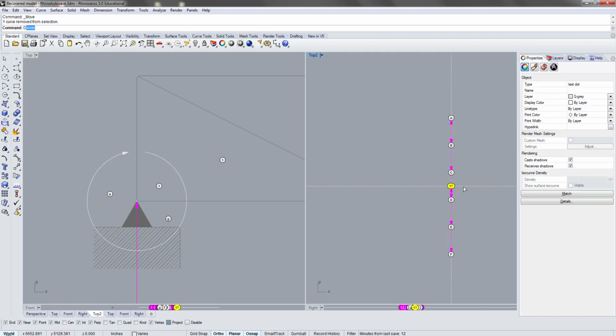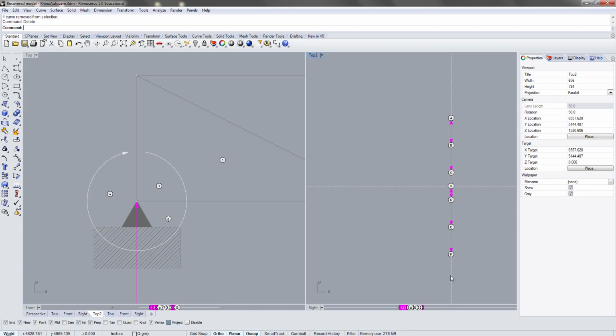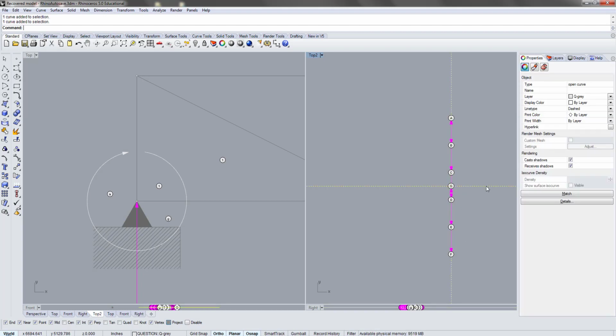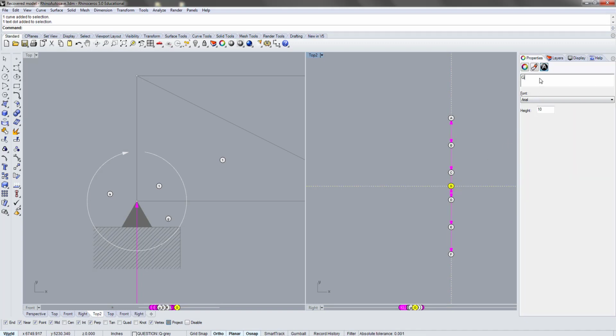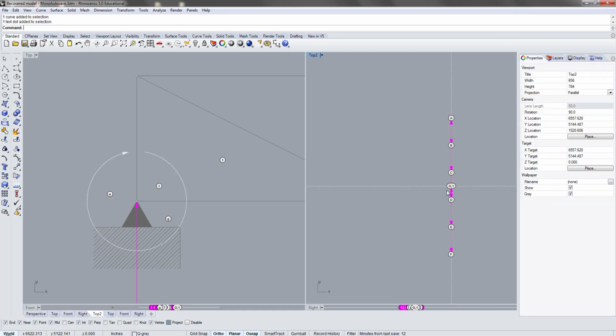So now what we know is that point 1 is on this vertical line as well as this horizontal line. So the logical conclusion is that point 1 is identical to point G. So that's G and 1. That means the force here, 1G, will not have any length. So that means the force here will be a zero force, and that is called a zero force member. In trusses, sometimes you find these members that have no force in them.